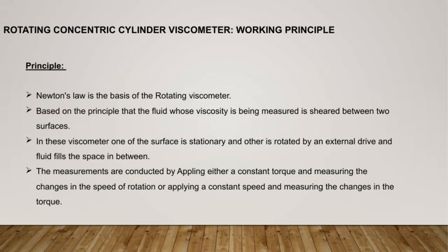Let's delve into the principle behind the rotating viscometer. At its core, it relies on Newton's law of viscosity, which is fundamental to how it operates. The idea is that the fluid we're measuring is sheared between two surfaces. Think of it like having a thin layer of fluid in between two plates. One of these surfaces stays still, while the other is rotated by an external drive. The fluid fills the space in between these surfaces, and as the rotating surface moves, it exerts a shear force